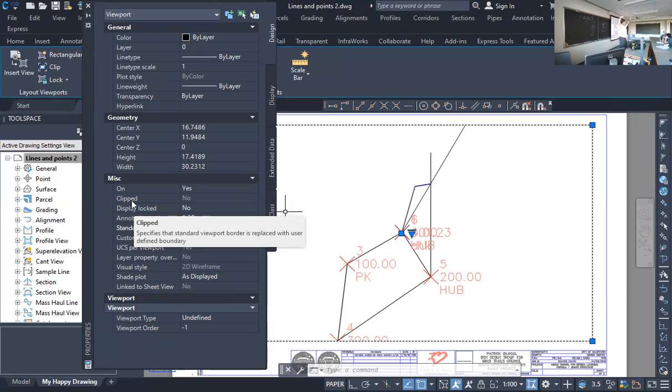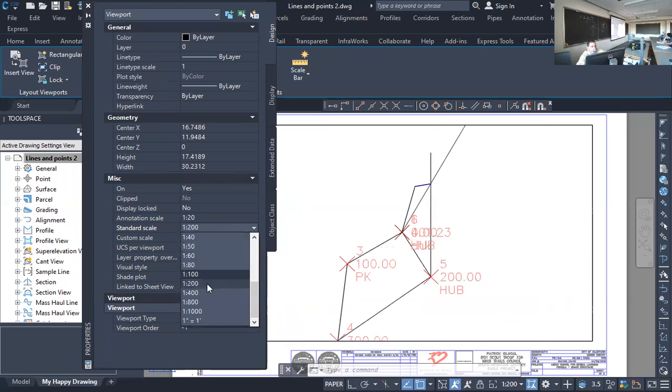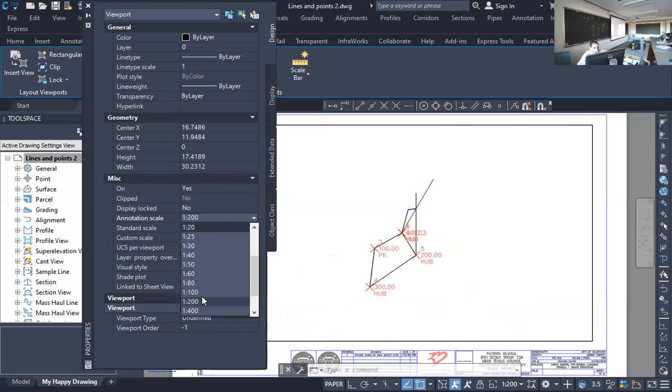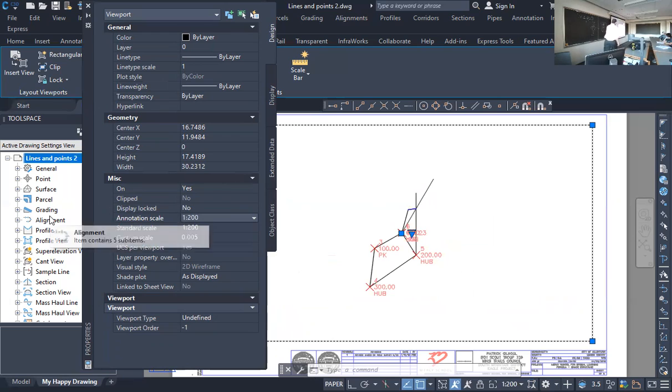For people that traverse a long distance, can you easily make me 2 drawings? One of the whole thing that you traversed out to, and then one of your loop that's a closer scale? Sure you can. Does it take long? No, all you're doing is changing one thing. So here, 200 works. Okay. Now I'm going to change my annotation scale to 200. You see how it changed my label sizes? So the label isn't like the whole sheet size, right? So those two should match.